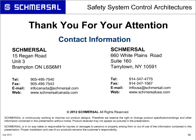And then there's the probabilistic approach, where SIL levels look at what is the probability of a dangerous failure occurring in the system. What ISO 13849 did was put those two approaches together to achieve a performance level.